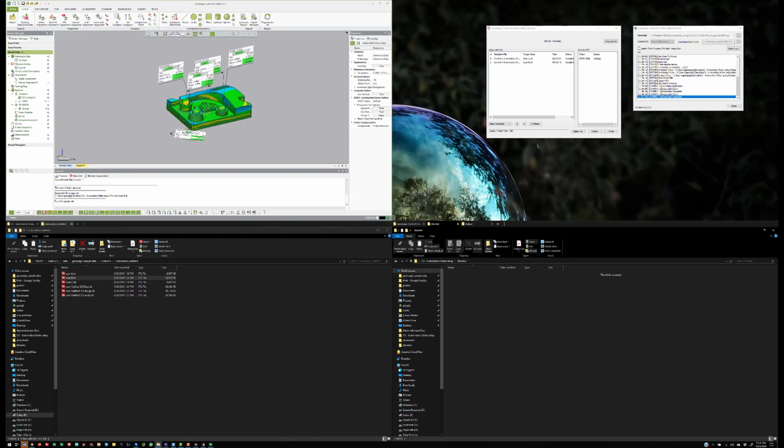So this is an overview of multi-part inspection with Control X. Again, there's manual, semi-automatic, and then fully automated inspection like this. So we talked about dragging and dropping a file in and updating. We talked about using multiple results to inspect multiple files. And then we talked about the batch processor, which will inspect a bunch of files all at once. Or you can set up a server, which will do it kind of on demand once the files are ready.